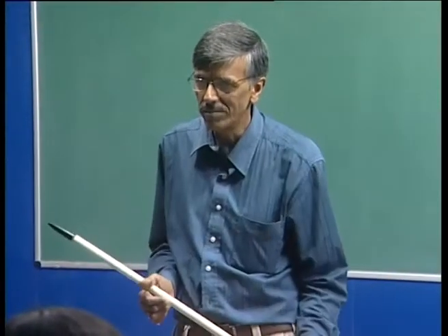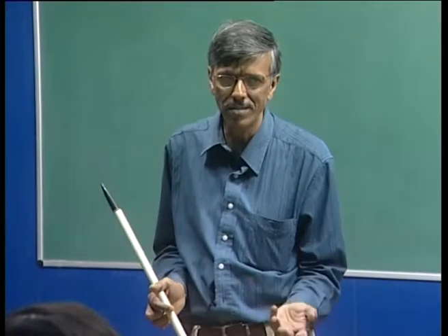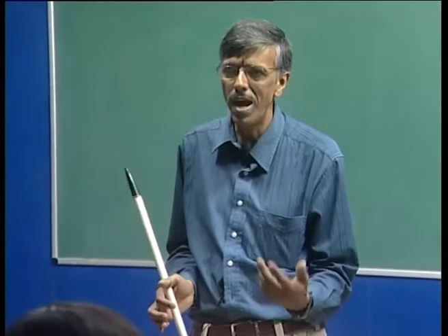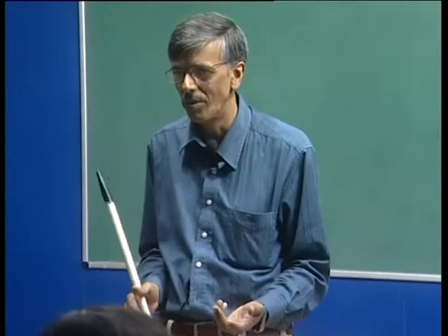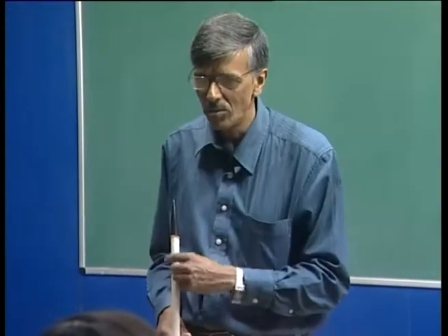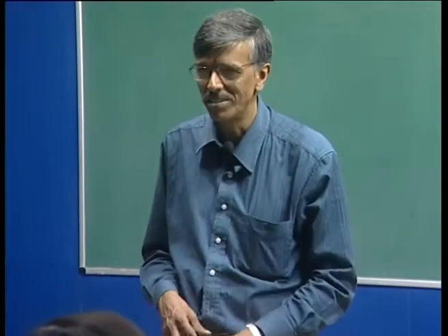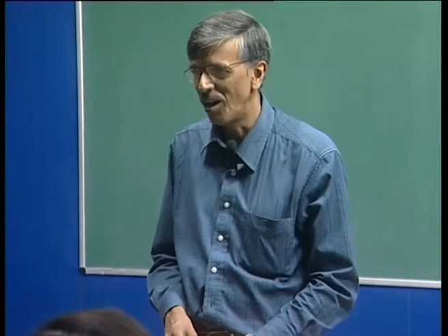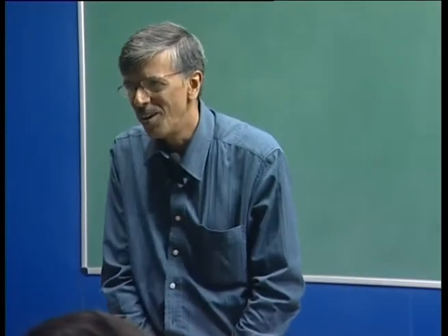What is the wavelength? What is our length scale here? Length scale is in terms of displacement thickness. So, if I have an alpha r, let us say 0.001, what is the corresponding wavelength? 2 pi by this, so 2 pi by 2 pi into 10 to the power 3. So, how much is it? Some 6,000 delta star. How many tunnels in the world are made where your test section is 6,000 delta star?